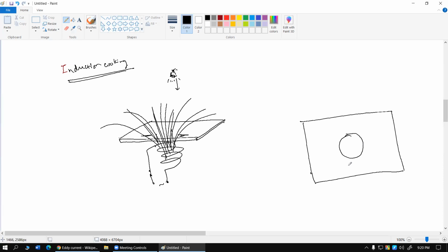So whenever we start to provide current to the solenoid coil, the EMF induction, meaning the rate of change of magnetic flux, the d phi by dt, the magnitude of this would be far bigger for this region. So we're going to have a bigger rate of d phi over dt because this is directly in the face of the magnetic field lines. Whereas on the other regions, the magnetic field cutting would not be as much. So these parts would have less induction.